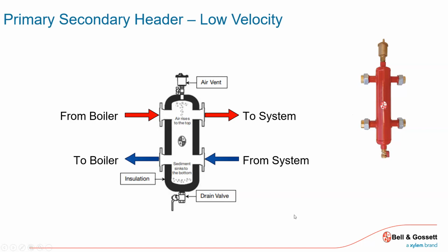It's a convenient location. But because of the low velocity to provide that low pressure drop for my primary secondary connections, which we'll explain in more detail later, the manufacturer said, hey, that's a pretty good spot to also collect any air coming out of solution out of my hot boiler water. So I'll collect it right here, put a high capacity vent on the top, get rid of my air, act as my primary secondary tees. So I'm killing a couple of different functions with this one device.